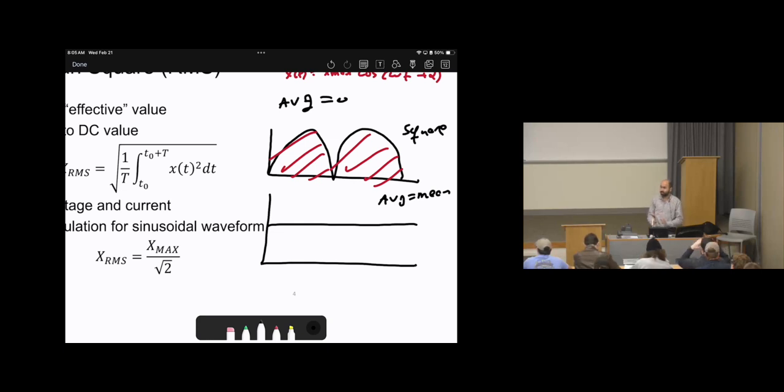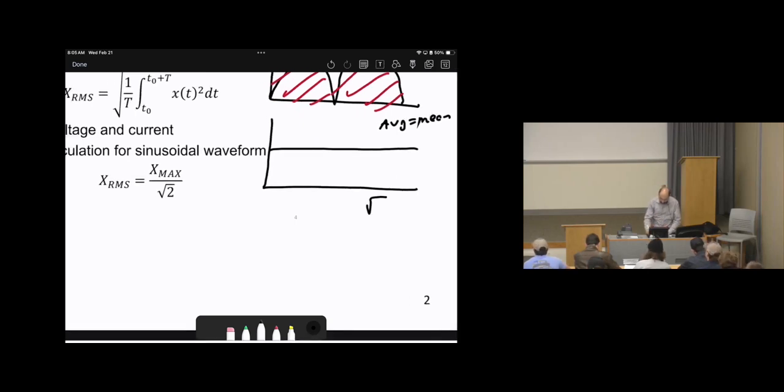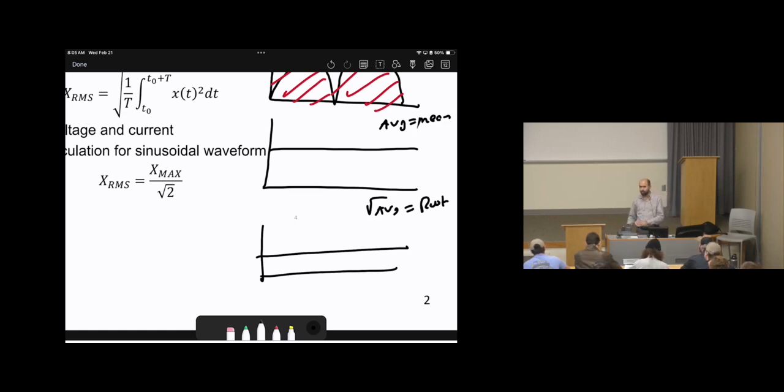Now, is this the value that I want? Not really. Why? Because this is the mean of the square. I squared the value and I took the mean. So how can I go back to the original? By taking what? The roots. Is this correct? So let's take the square roots, the root of the mean, whatever, like take the roots. Then we will get a value that's non-zero, and it is something equivalent to the average.